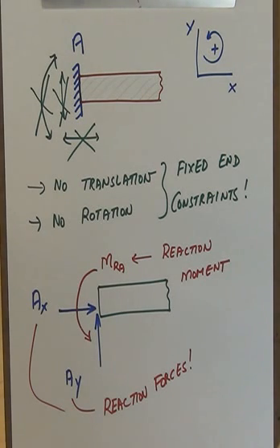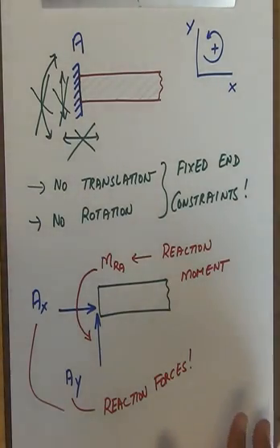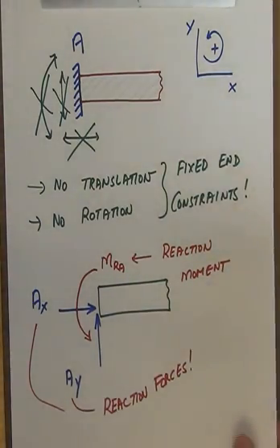If I put any other kind of a support, then that's called over constraining the rigid body, and this becomes an over constrained or a statically indeterminate problem, which means that we need to come up with some other set of equations to help us solve for the support reactions. We will look at such problems when we do mechanics of materials, where we look at fixed beams on walls, and then we will make use of certain kinematically useful equations in terms of displacements of one end with respect to the other. So for the time being, we will not worry about such things.